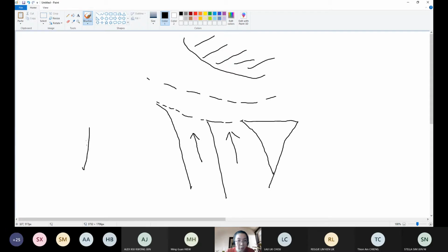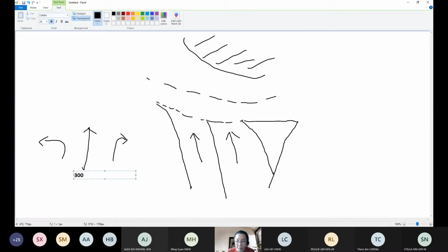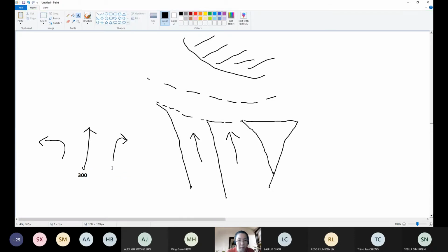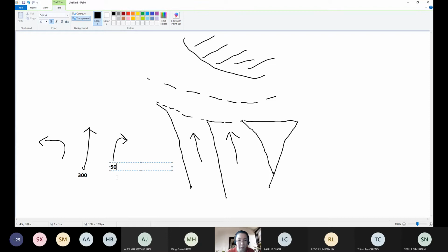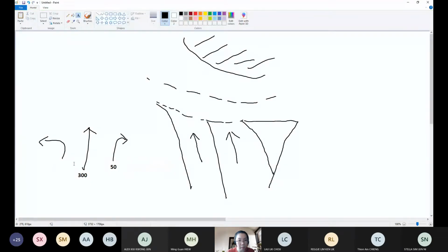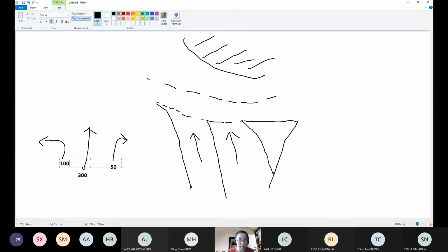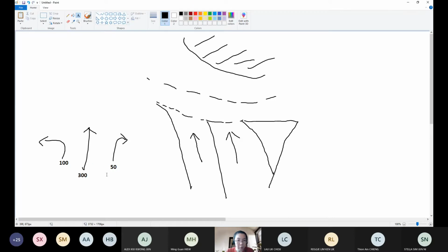Okay, so when you have 3 volumes: through, right turn, and a left turn volume. Let's give some numbers so that it's easier to understand. This one is 300. Through movement is 300. And then this one we have 50. And this one is, say, 100. Okay, so now if this is a single lane, the entry flow would be 450. Just add everything up.